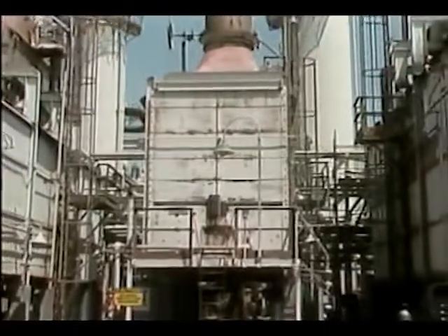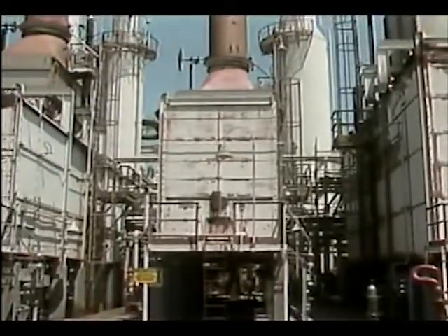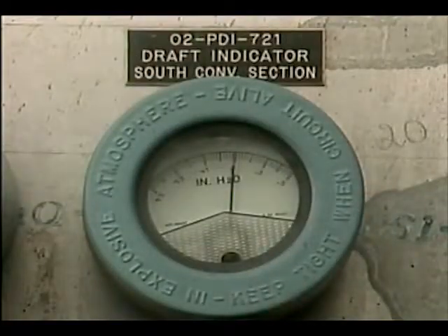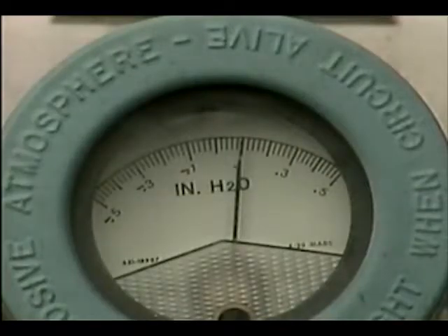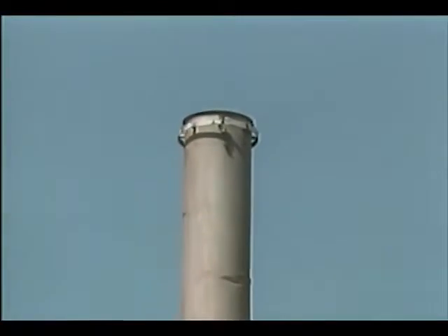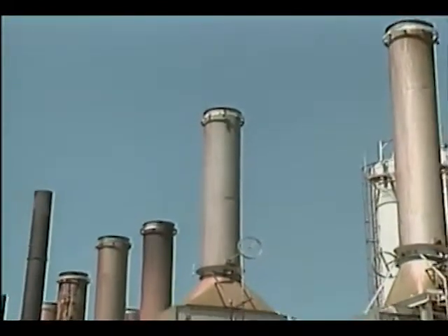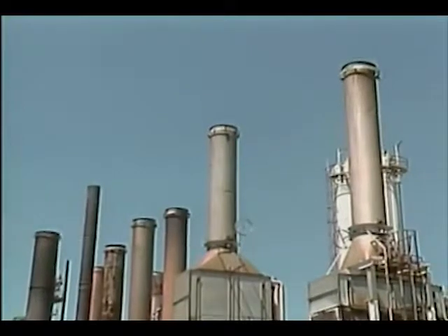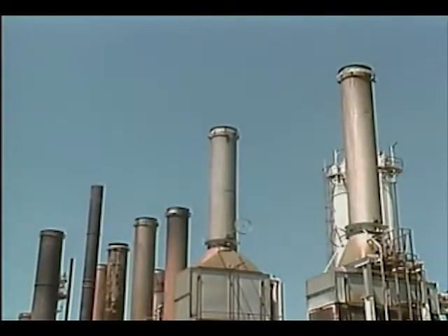The pressures in various areas of a furnace are typically measured by instruments called draft gauges. Draft gauges commonly indicate pressure measurements in units of inches of water. These gauges are used to determine the flow of air and combustion gases through the furnace. In a natural draft furnace, the height of the stack affects the amount of draft that can be produced. In general, if all other airflow conditions are equal, the taller the stack, the greater the draft. This is because a taller stack creates a greater difference in pressure.